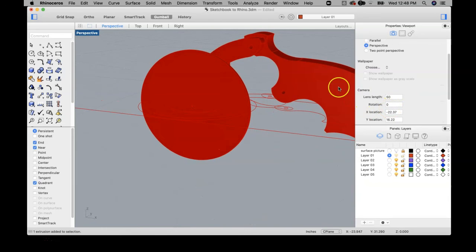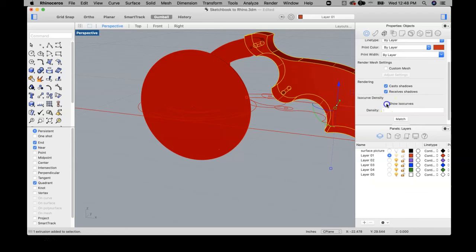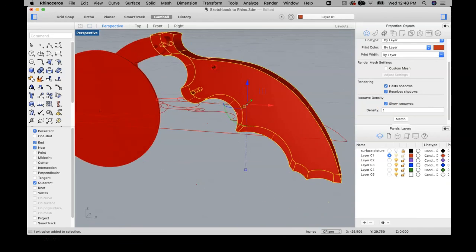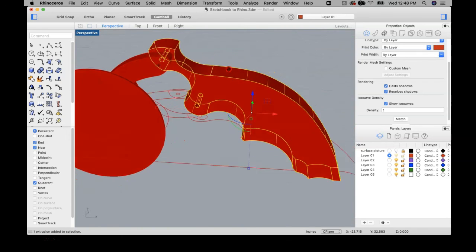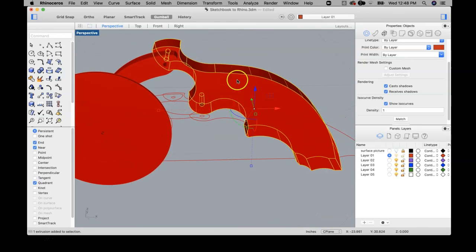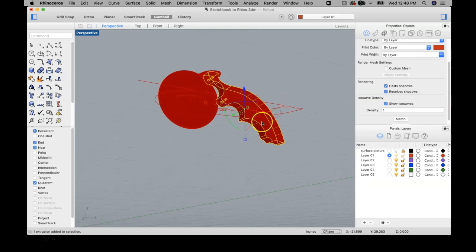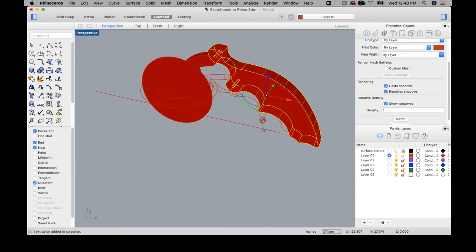It just shows you where every single one of those points was located along that control point curve. That's why you can see where your model could get a ton of ISO curves and kind of choppy looking if you put in too many points. So just be aware of that, so you wind up with some clean objects in the future.